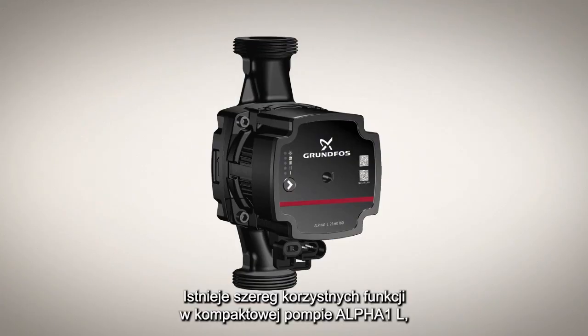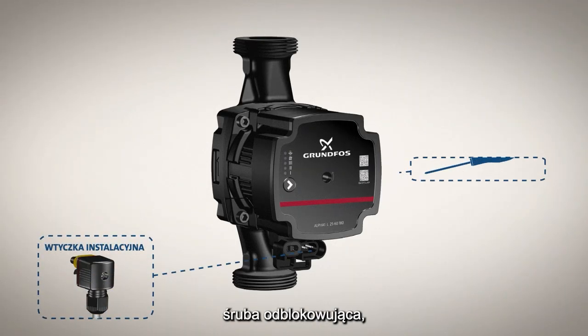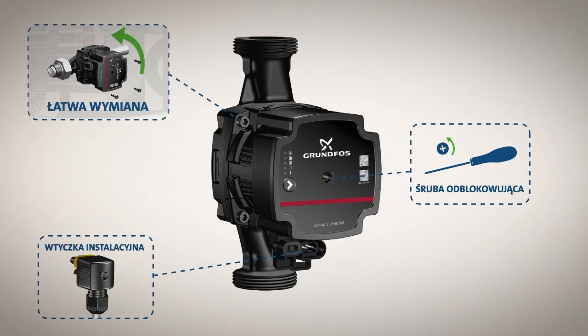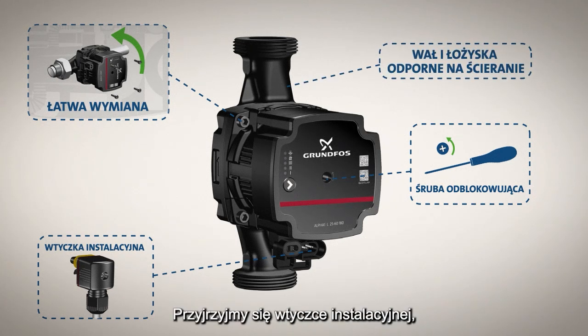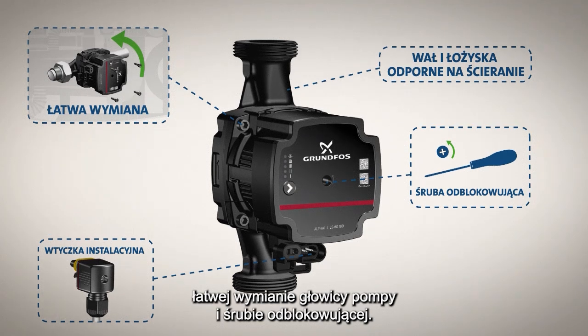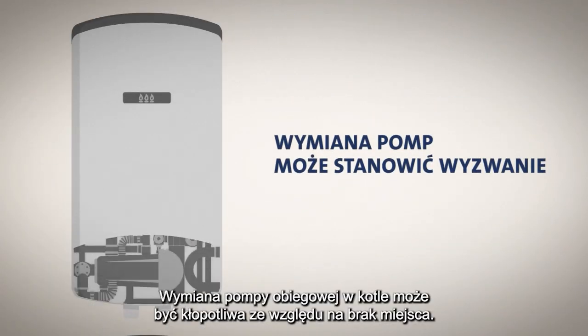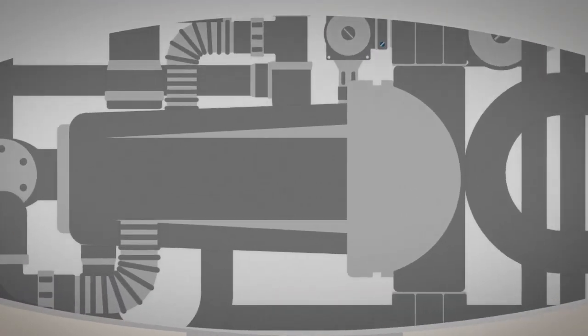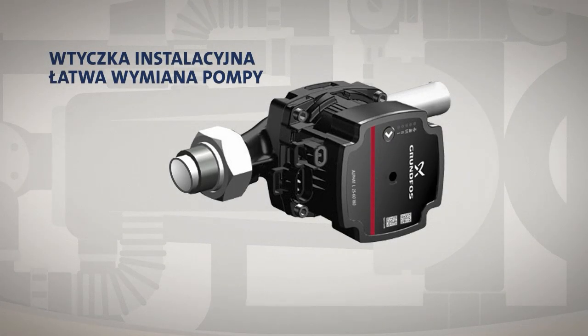There is an array of beneficial features in the compact Alpha 1L, including an installer plug, a deblocking screw, easy pump head replacement, wear-resistant shaft and bearings, to name a few. Here we will take a closer look at the installer plug, easy pump head replacement, and the deblocking screw. Replacing a circulator pump in a boiler can be a hassle due to the lack of space. The new installer plug and the easy replacement of the pump offers a solution to these concerns.